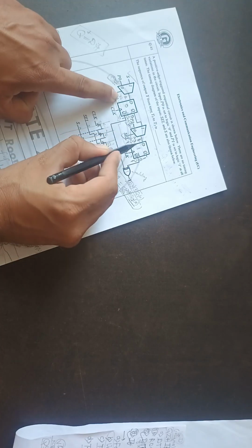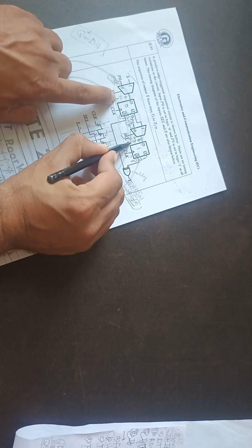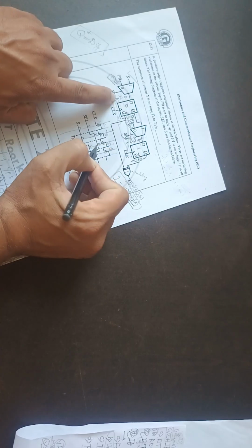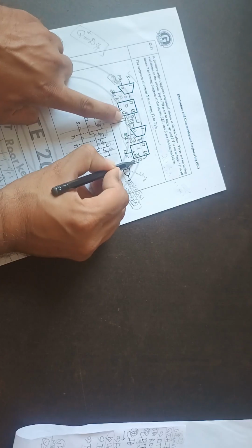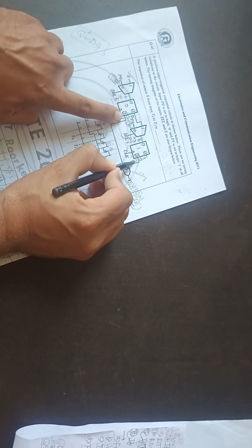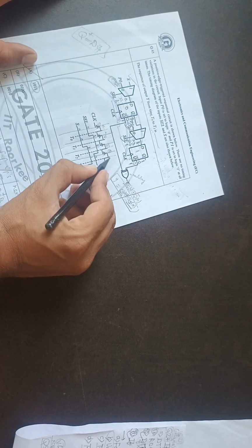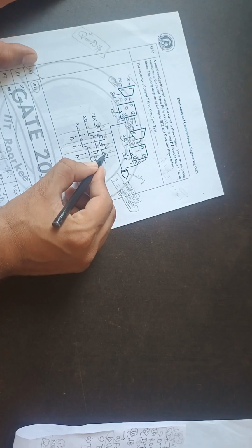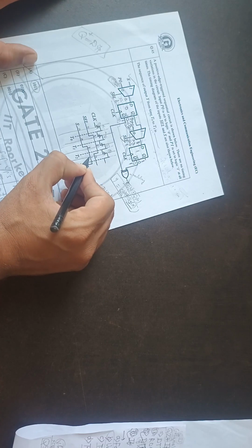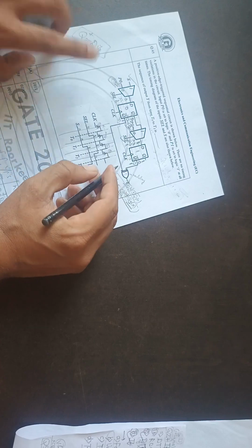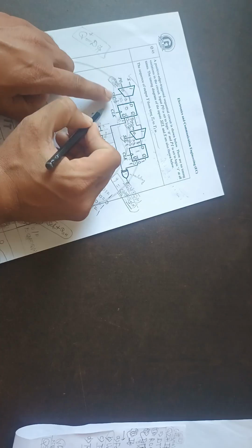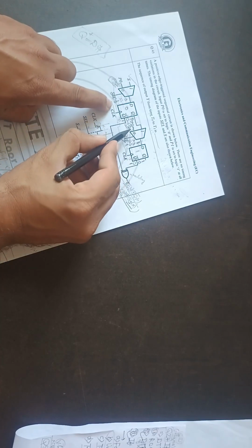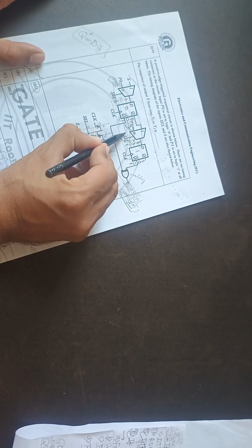The previous bit was 0, so 0 will come. So the input was 1 0, and just after the clock edge, this 1 0 will transfer as output 1 0. So after the third clock edge, the output of both flip flops will be 1 0. Okay, and just before the fourth clock, select is 0 and S is 1, so select is 0, so this part will come here, and select is 0, so this previous thing will come here.